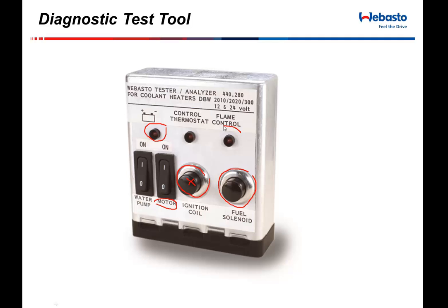At that point, the flame control light will come on, indicating that the internal photocell has changed resistance. If that light comes on kind of dim, it's changing resistance dimly. It's starting to get a little bit of a carbon coating over the top of it, which is the reason it's not fully changing resistance and not giving you a full red light.